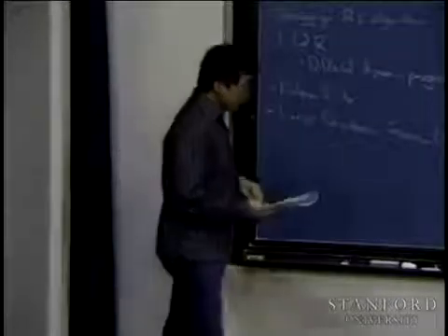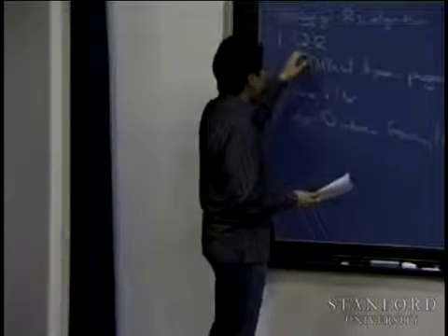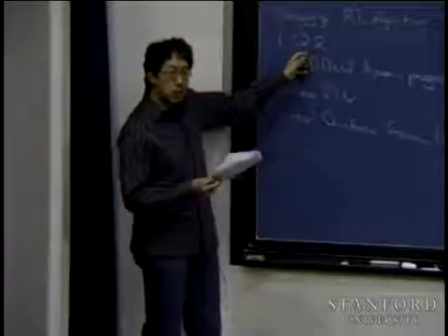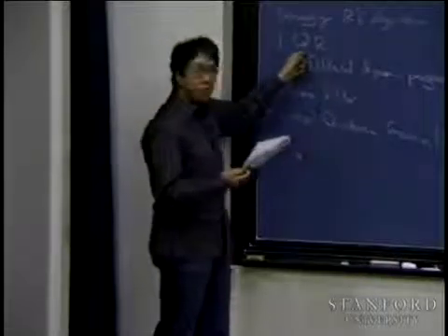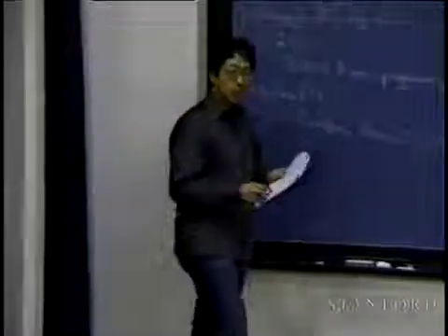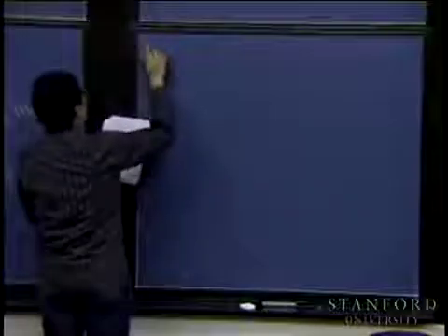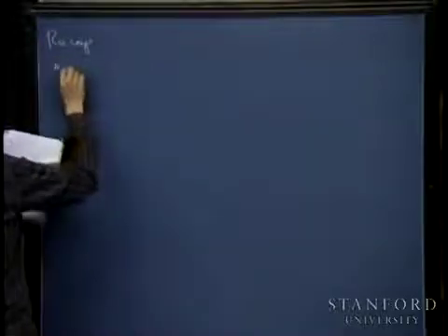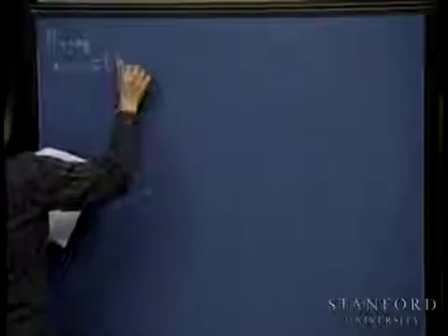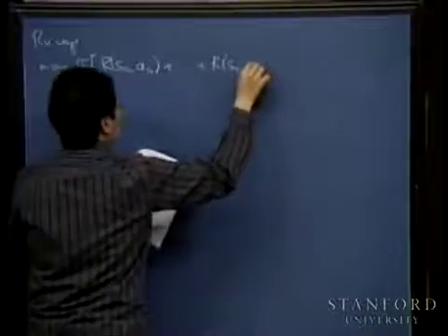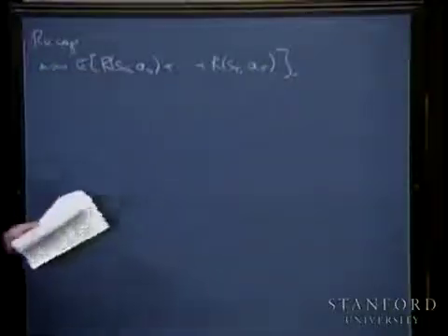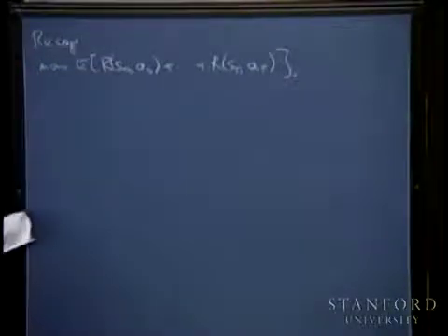So let's go back to our discussion on LQR control, linear quadratic regulation control, and then I want to take that a little bit further and tell you about one variation on LQR called differential dynamic programming. Just to recap, to remind you of what LQR is: in the last lecture, I defined the finite horizon problem, where your goal is to maximize the finite horizon sum of rewards, and there's no discounting anymore.